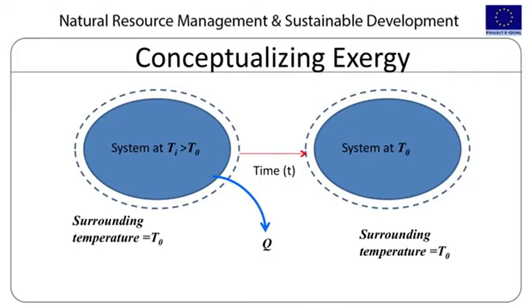By analyzing the amount of exergy destruction in an equipment or within a process, we can see where we should focus our efforts to improve system efficiency and to utilize maximum of natural resources. It can also be used to compare various processes or systems and helps to take decisions regarding design parameters of any thermodynamic processes. Now the question is, what is exergy? Conceptualization of exergy is important.